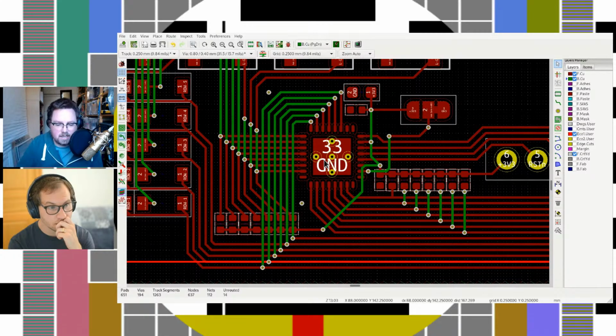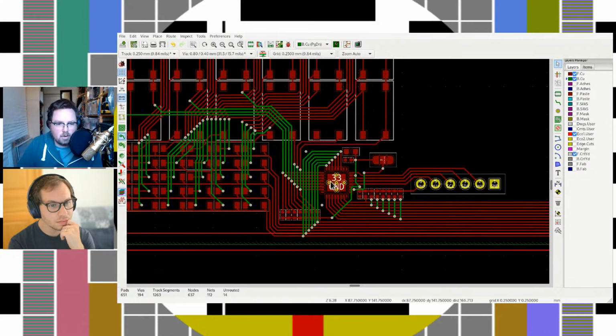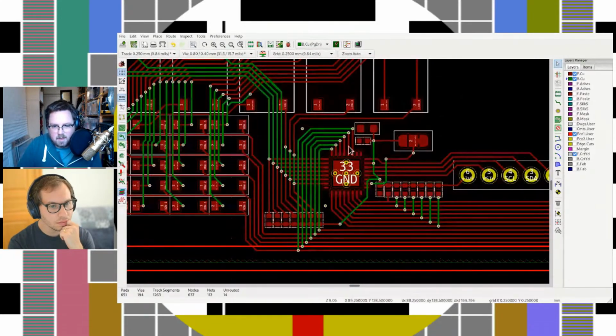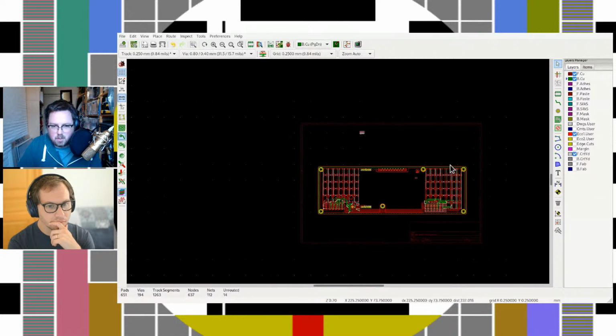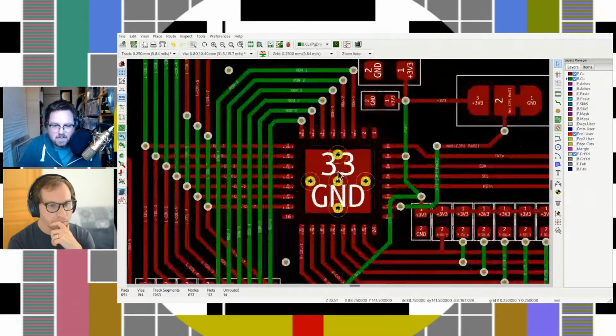So it's basically like a serial port controlled 24-pin expansion port. So you can wire the 24 pins necessary for the keyboard into here, because I end up having something like 5 rows with like 12 columns or something like that, just to keep the layout easier. And so those 17 pins fit in the 24 pins that are on here, even with some spares.